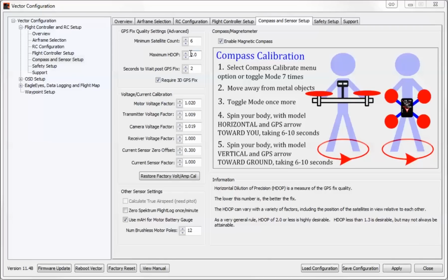One thing that people always fail to remember is that GPS satellites aren't always directly above you, they're actually on the horizon line as they're coming around the rotation of the Earth. So potentially, if you've got lots of trees around you, when you get above those trees, you might actually get a slightly better signal. The one thing you've got to bear in mind though is that getting a signal on a multi-rotor that's moving around a lot might be quite challenging, so just bear that in mind.